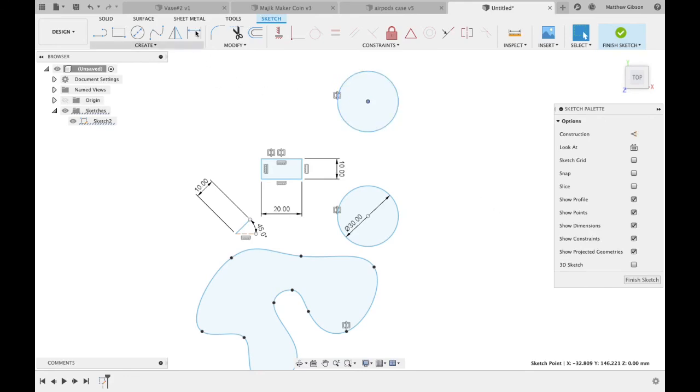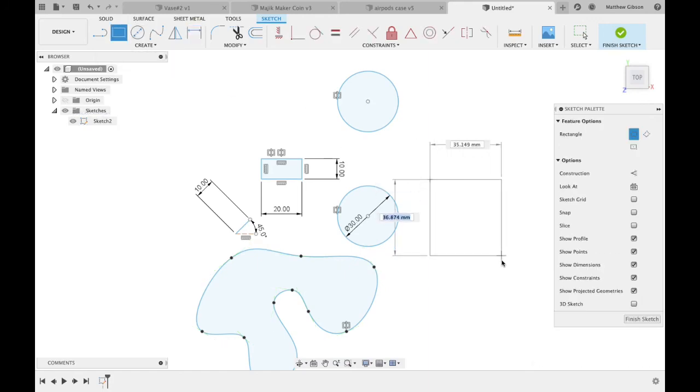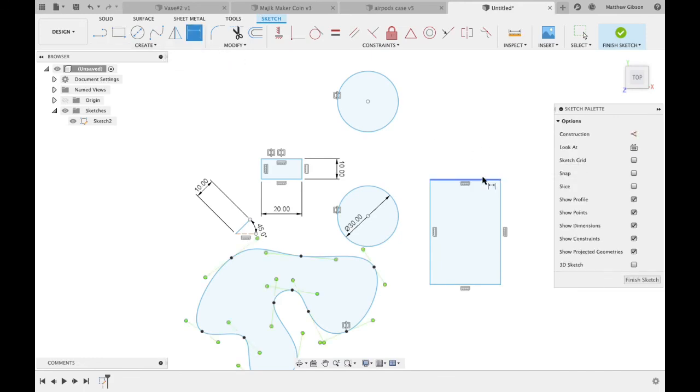Now the last tool in this create menu is the dimension, and you can use that to, let's say you create a square and you want to enter the dimensions in later. So let's say you create a square, you don't care about the dimensions now, but if you go to dimension it, you can select this line and this line, and then you will be able to enter the dimension in there.